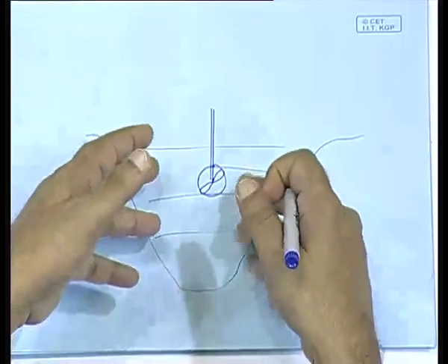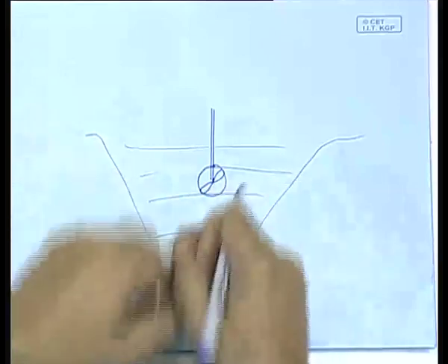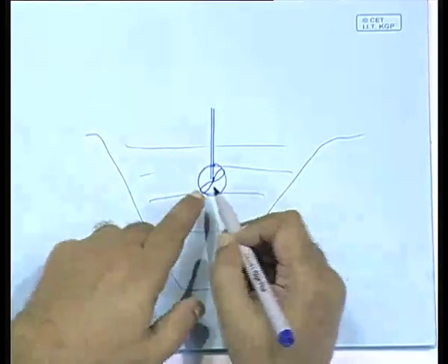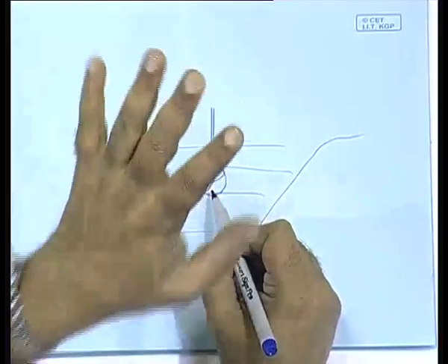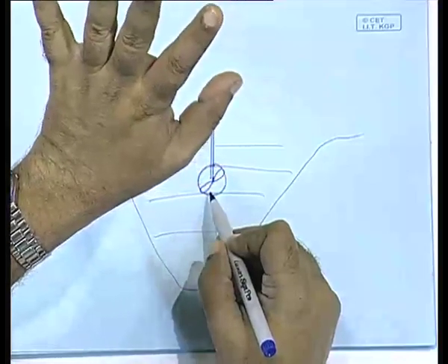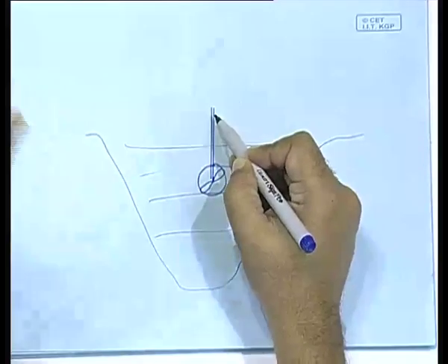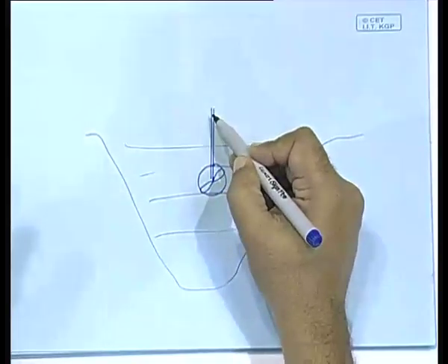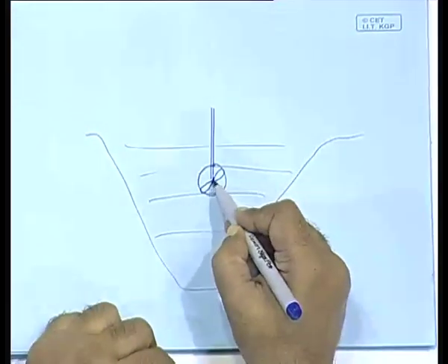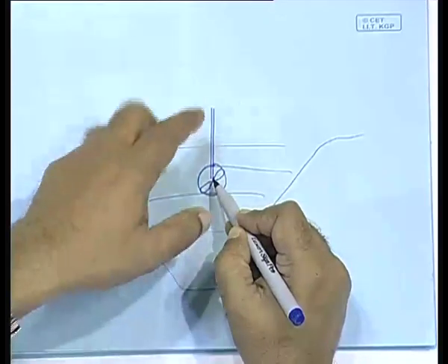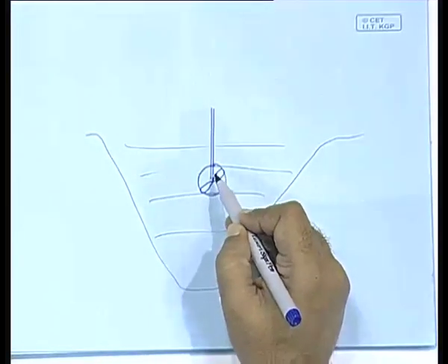so that the rotation of the turbine will be proportional to the flow rate, and since this does not produce much of an obstruction, it by itself will not create much turbulence. So if you have simply a tacho generator connected, you can measure the flow rate at different places by simple electrical measurement. This is called a turbine meter.